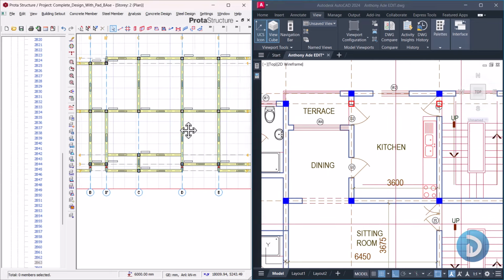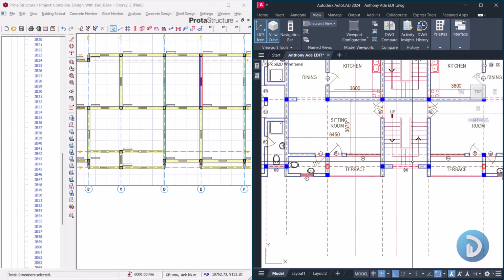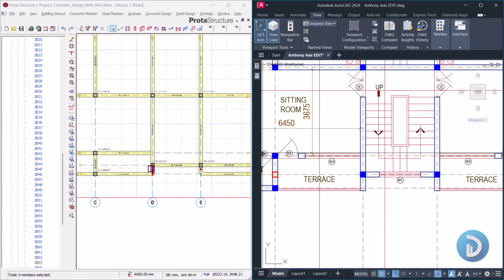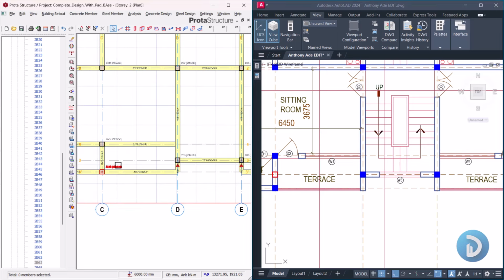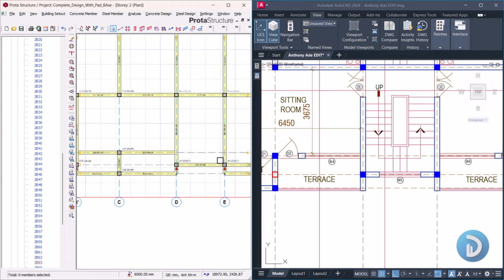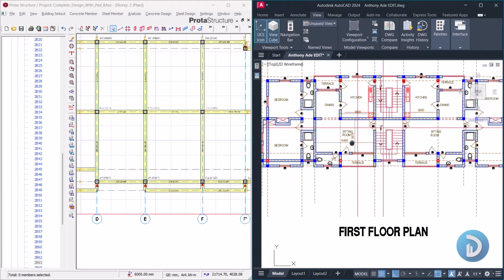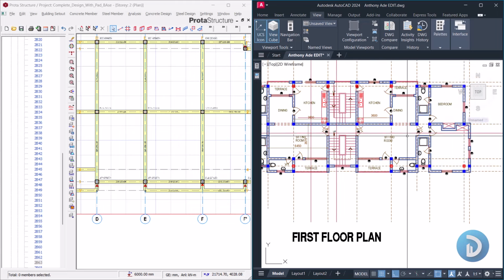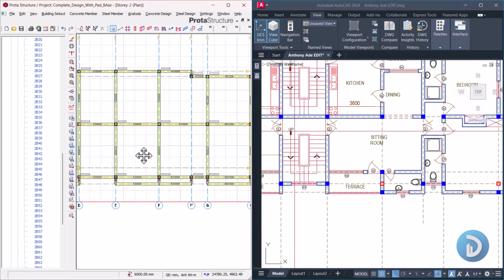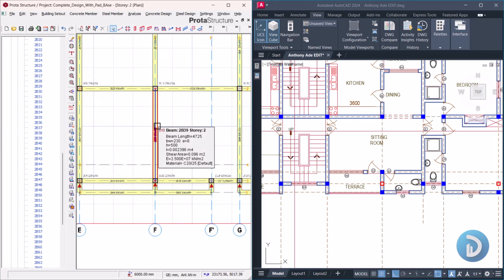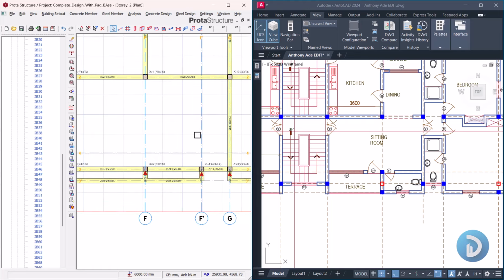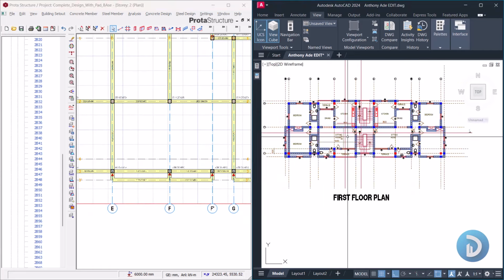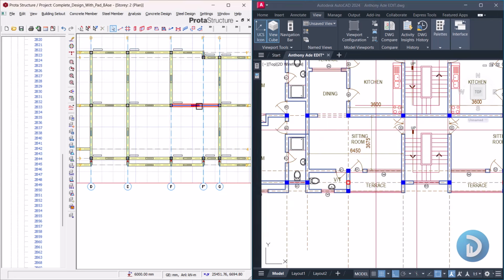Okay, so we've made this modification, and the next is this part. Okay, this is actually okay. This staircase area, we have this column here, which cantilevers to join this column, so which also cantilevers to join this. Okay, so we also have to make the same modification on this other right hand side. So that will require us taking out this beam. We'll delete this, and we'll also create a column at this position.